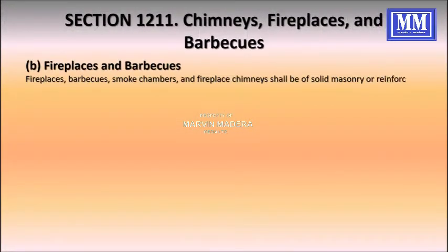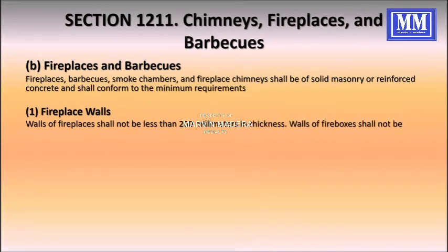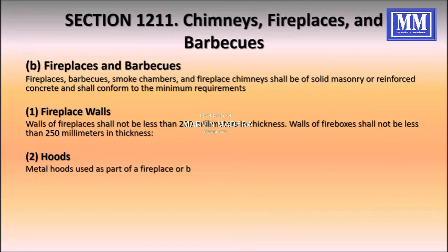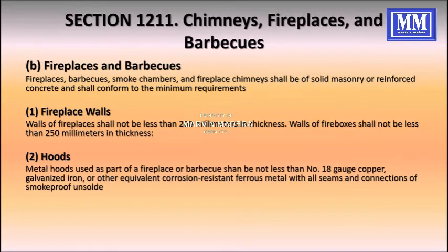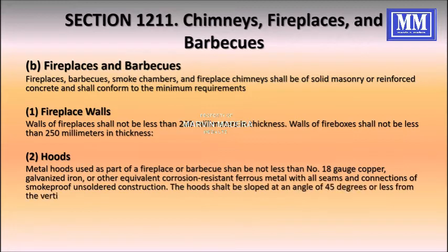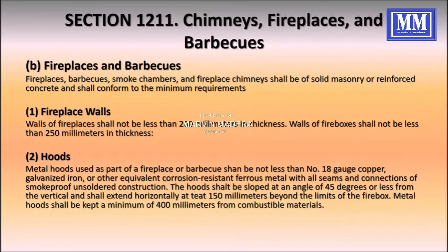Fireplace, barbecues, smoke chambers, and fireplace chimneys shall be of solid masonry and reinforced concrete and shall conform to the minimum requirements. For fireplace walls, walls of fireplace shall not be less than 200 millimeters in thickness. Walls of firebox shall not be less than 250 millimeters in thickness.